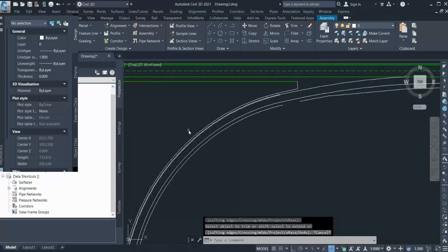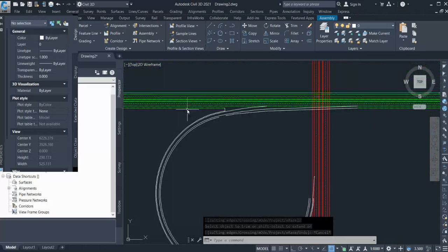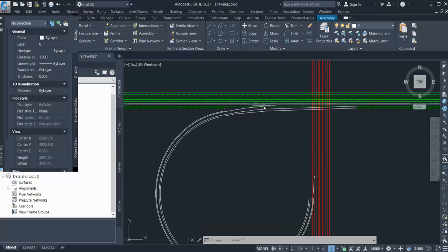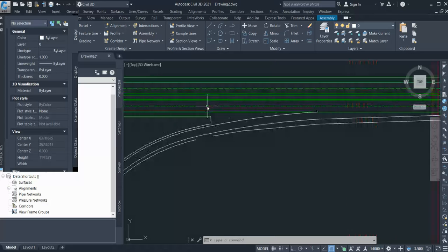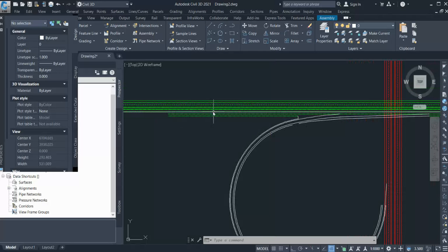Now in some cases you also have earthen shoulder, depending on how you are designing, whether you are going with the total RE wall, and you are going some point here with the earthwork, or you are going completely with the RE wall. So you have to decide where you start with your earthen shoulder as well as some point where you start with your earthwork slopes as well. And the same thing will go for this also. At what point it will start with the earthen shoulder and earthwork slope.